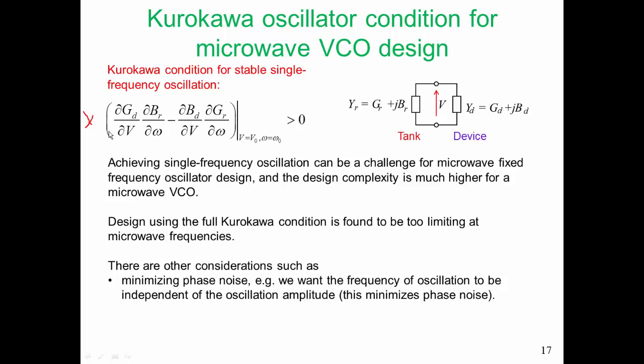That is absolutely important. We must minimize the DC power consumption, and the reality is that oscillators have fairly low efficiency. Comparing the RF power coming out to the DC power going into the oscillator, the efficiency is really quite small, maybe a few percent. Of course, we could follow our oscillator by a fairly efficient amplifier and boost the overall efficiency, but the oscillator core itself is fairly inefficient.